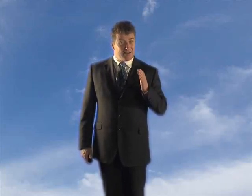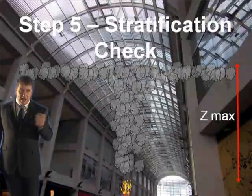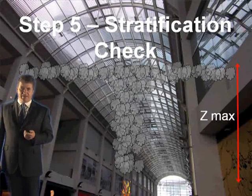Now again, this is a high temperature, as you would expect with a 5 megawatt fire leaving the opening, as there is not much entrainment. Even though the entrainment's been increased by the downstand, it's still not as much smoke coming in there. This is not a problem though, again, because the temperature of the smoke will not affect tenability in the shop, as the shop should meet acceptable travel distances. This is about getting the smoke out of the reservoir within the tenability limits. The shop should have already been evacuated. In other words, you've met your acceptable travel distances. That covers step 4. Let's move on to step 5 now, the stratification.